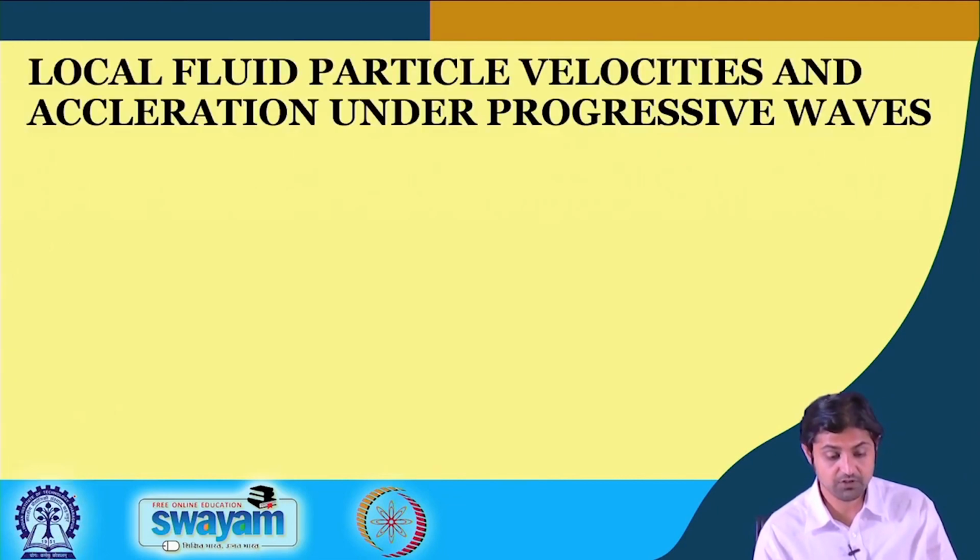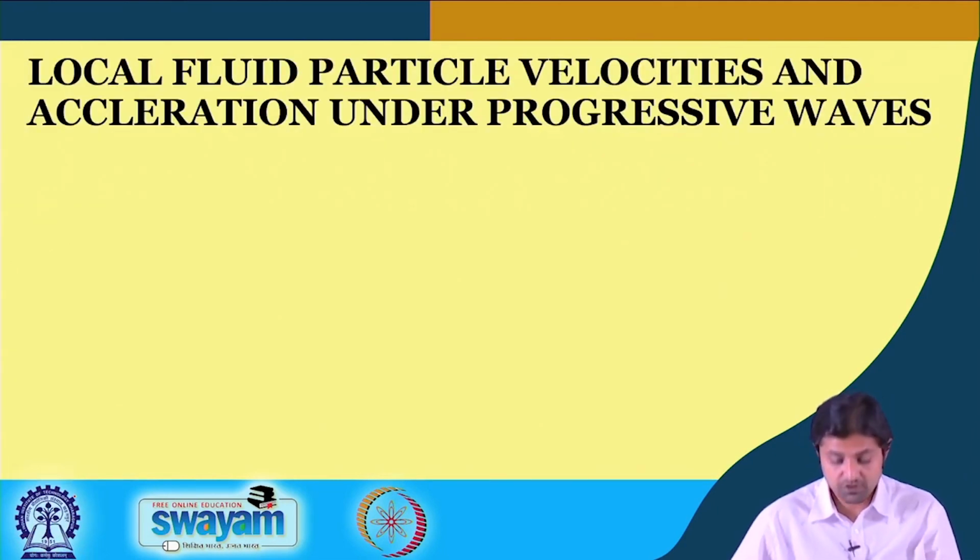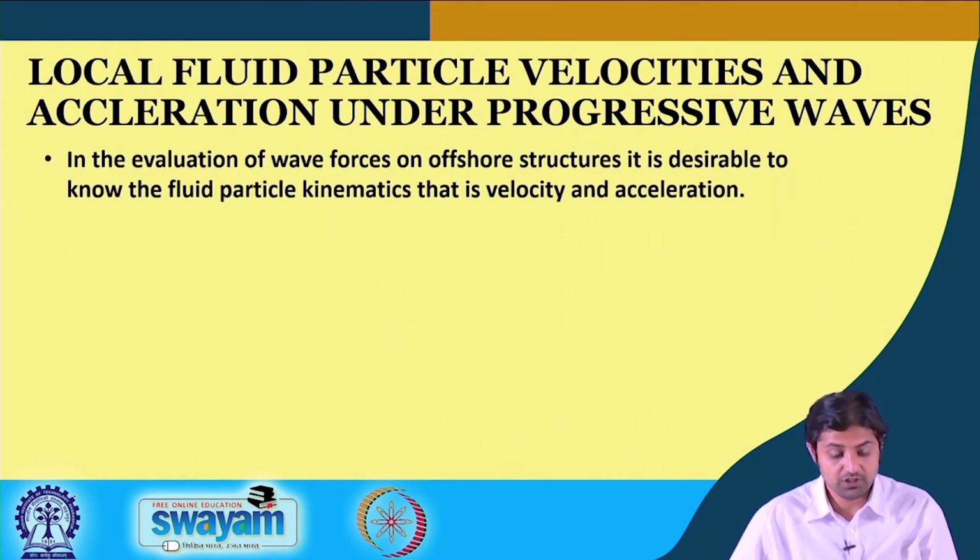All right, proceeding forward. Now, we have found out the velocity potential, we have found out the dispersion relationship. Now, it is time to find out the local fluid particle velocities and accelerations under progressive waves. More importantly, why do we need to find out these velocities and accelerations? Because in evaluation of wave forces on offshore structures, it is desirable to know the fluid particle kinematics, that is velocity and acceleration.